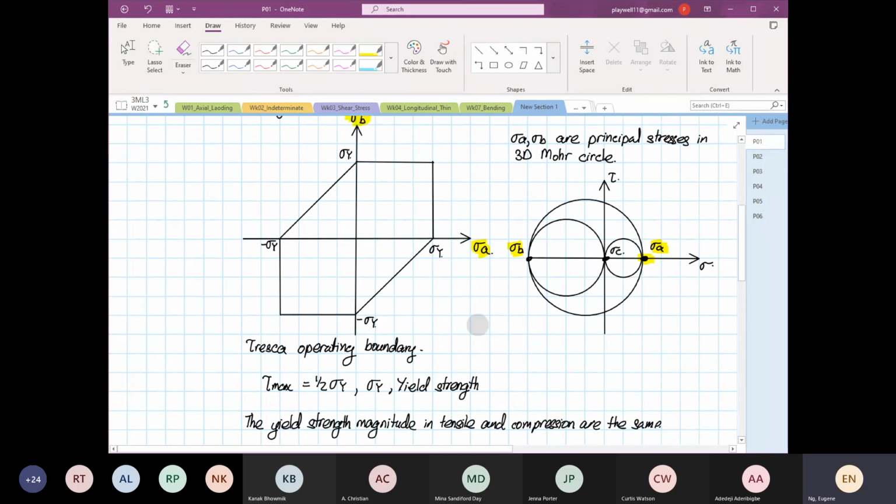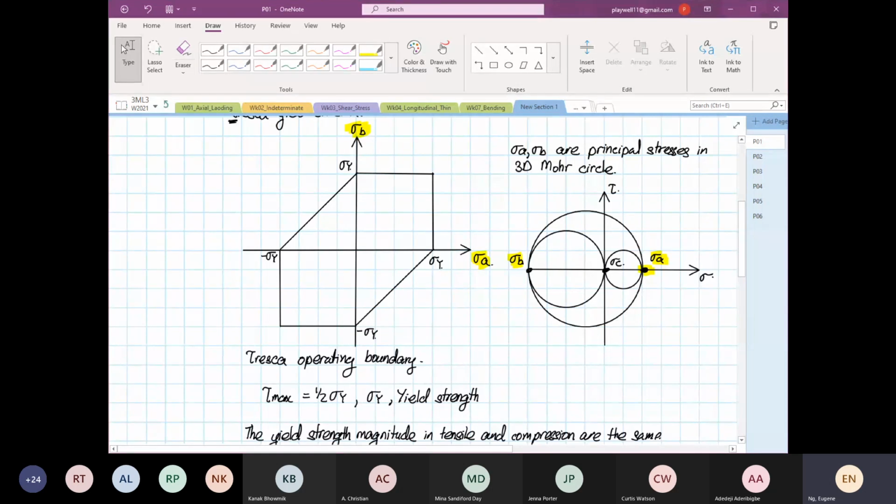That's why if you look at the values, which I'm going to highlight, compression and tension, if you look at the scale of proportion, it has 4 small squares on the right-hand side, the same, and in the vertical scale, the spacing from the 0 point is the same. So it makes the assumption that the tensile and the compression strength are the same. Now this will not work especially for concrete, for civil engineers.